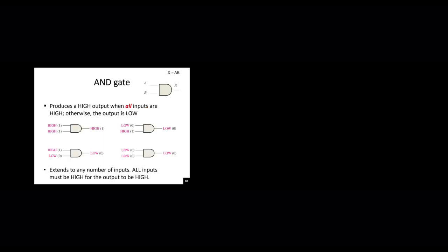And you need to do that using circuit elements, which are called gates. So an AND gate is simply a digital circuit which does the AND operation for us. So we have two inputs, our logic propositions, A and B, and we're going to input a low voltage or a high voltage, depending on whether we think that proposition is true or false. So if we have a low voltage, it means 0 or false, and if we have a high voltage at that pin, it means 1 or true.